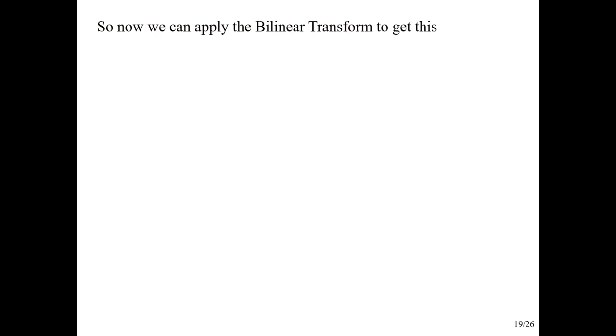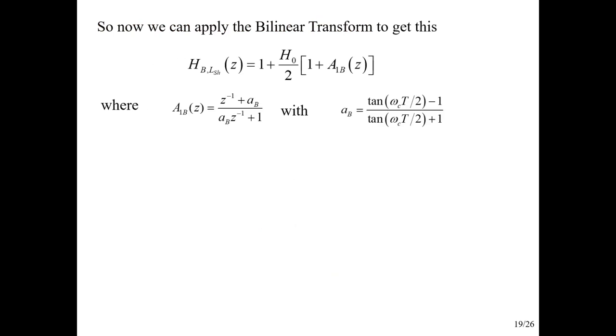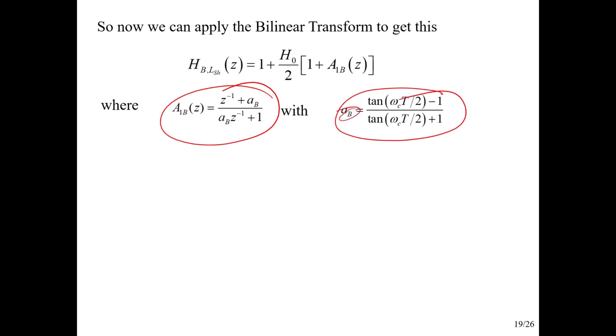Well, one thing we need to do is get over into the discrete time world. So we're just going to apply the bilinear transform and get the all-pass filter here. And I'm using the B here to denote that this is for the boost form. So here's our classic first-order all-pass filter, but how we compute the alpha is specific for the boost form.